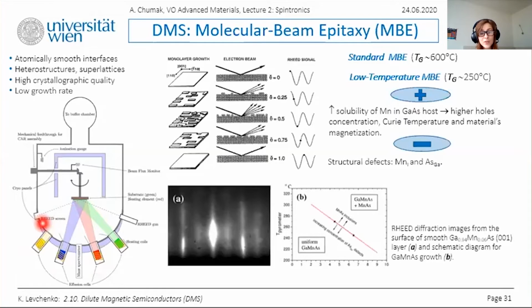The presence of this ultra-high vacuum also allows for the incorporation of various in situ methods like RHEED, reflection high energy electron diffraction, or LEED, low energy electron diffraction, also mass spectroscopy. And when combined with non-UHV-specific techniques like ellipsometry, pyrometry, and band edge thermometry, this MBE becomes a very powerful tool to study basic science and for the production of high quality materials.